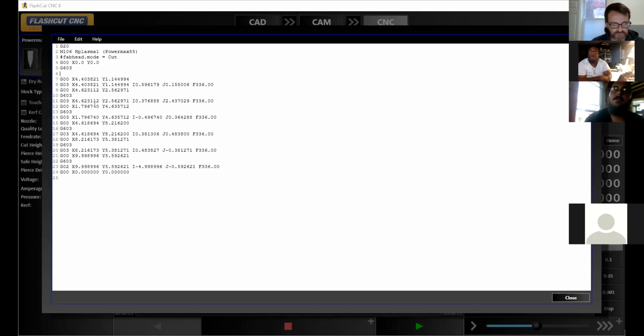We're going to punch in our begin grid. Let's say we want 4 columns, 6 rows. We'll start it at 0.5, 0.5, so it's off the axis. We need 10.5 inches of spacing in the X direction, 10.5 in the Y, because our circle was in fact 10 inches. We'll build it row by row, and we'll cut in a zigzag pattern.